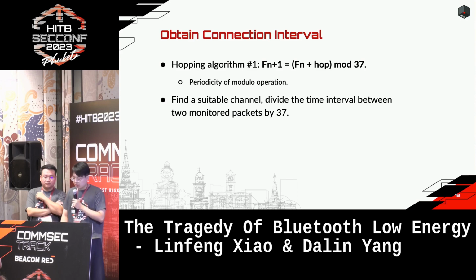And the connection interval determines the interval between frequency hops, which is critical. To get this parameter, we first need to understand the channel selection algorithm a bit. Here I take channel selection algorithm 1 as an example.